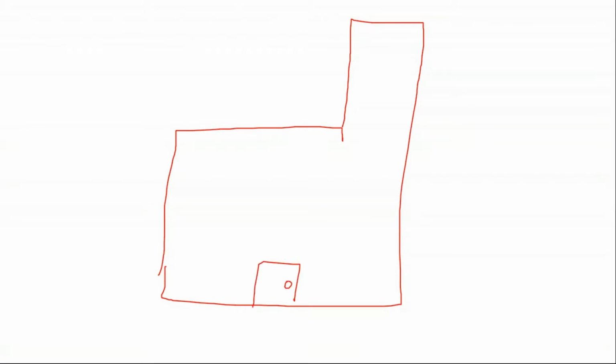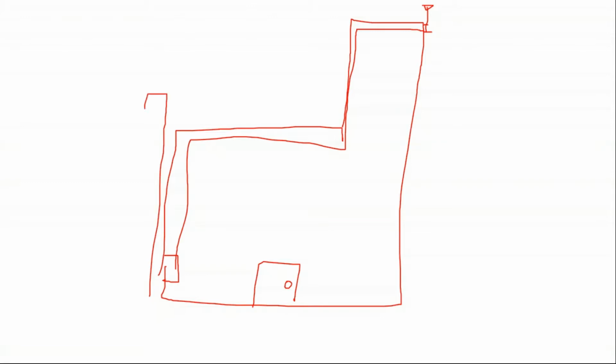Say this is the area that we actually want to mount the antenna on top of, because that's going to give us the best height. The problem that we need to think of here is, if the control cabinet is at the opposite wall, all the advantage that we have on the height here is lost in having to add the extra coax cable to the system. So there are different solutions we need to come up with. Maybe we find that putting a pole on this side of the system will give us enough height and is close enough to the control cabinet.